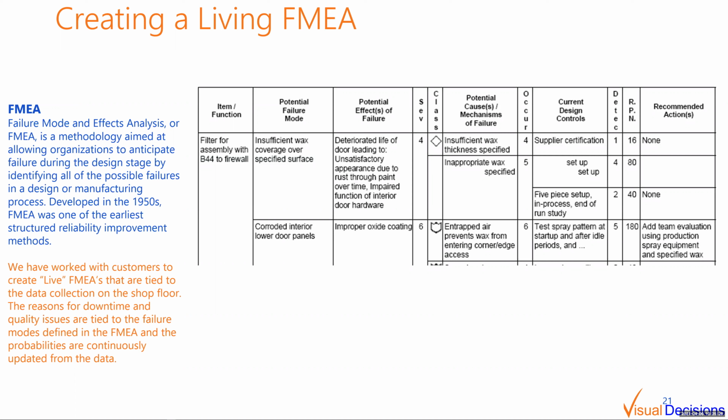Now, for a probability of detection, that's a little bit different. You have to figure out, how do I optimize my probability of detection? But utilizing the IIoT systems and the flexibility that they have, you can actually use this to directly connect to any tag or any information about the process that is accessible. You can add vibration sensors or whatever else you need to in order to determine that particular failure mode is occurring.